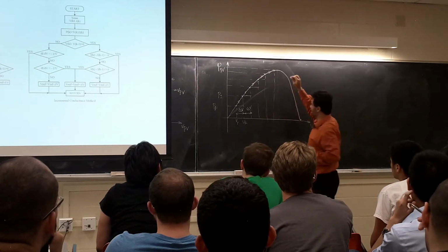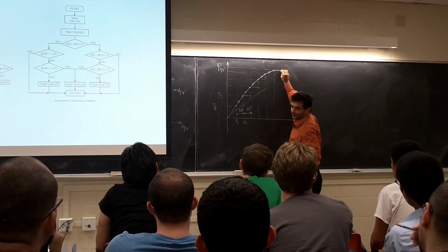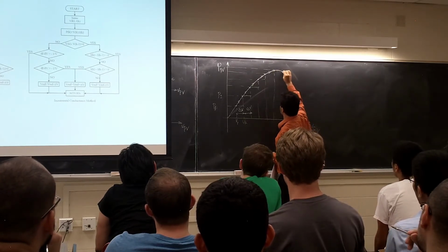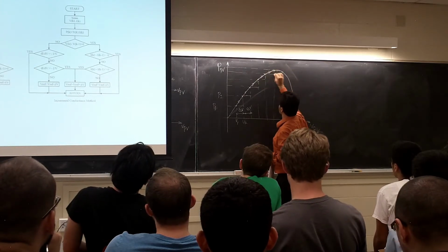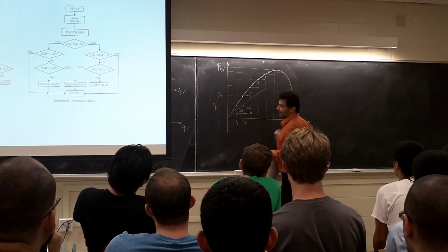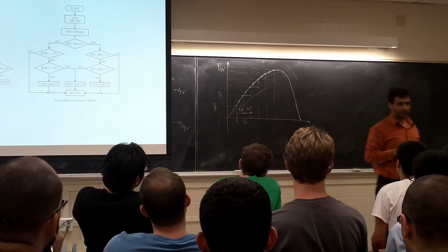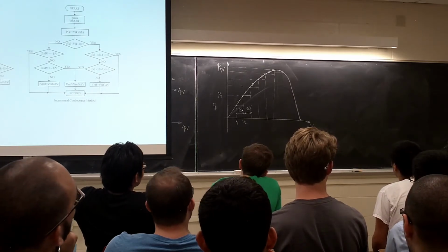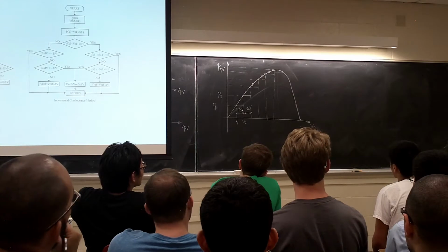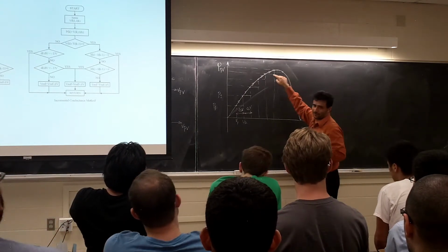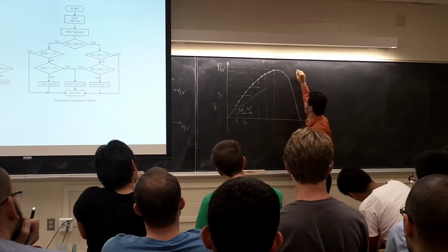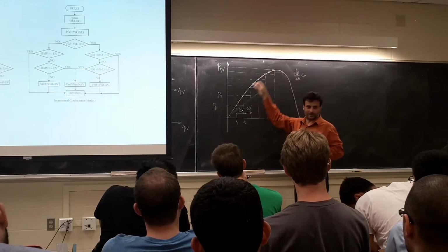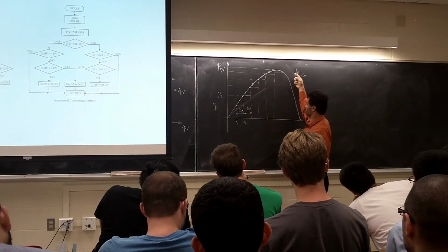Accuracy, right? If I am here, you jump here. I want to make sure, so now here, look at here. What happened? Delta V is positive, power went down, delta P is negative. So it says, hey, you are going the wrong way. Go back. You are increasing the voltage, and as soon as you are here, it says dP over dV is negative. Here, dP over dV was positive. So basically, now it says go back.